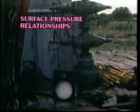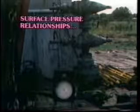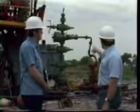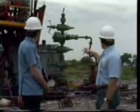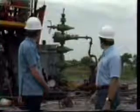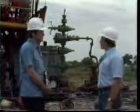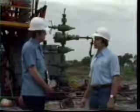Deliverability relationships using wellhead rather than sand face pressures are useful because they are directly related to surface conditions, that is, to the gathering system back pressure. Off of our Christmas tree, we have also a small looping wire coming off that goes to a deadweight gauge that is a very accurate pressure measurement instrument. And so we measure our pressure at the surface off of the Christmas tree. So you're measuring surface pressure, and later you'll convert to sand face pressure when you get all this information back to your offices. Right, to get the bottom hole pressure.